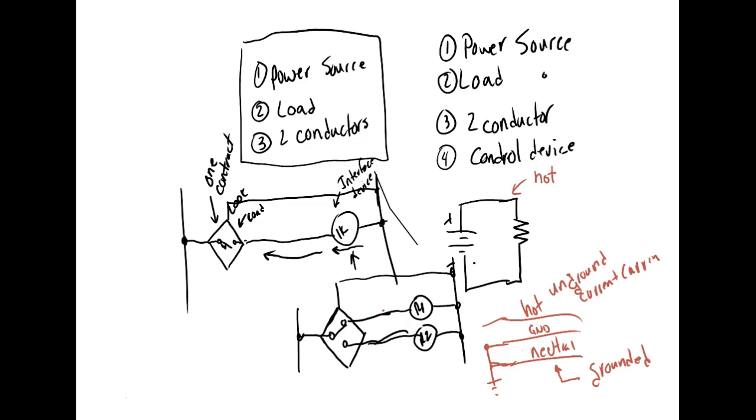Power up. Now make sure with your ohmmeter you don't put power into a circuit, so make sure you don't put your ohmmeter in here. What you're going to do is hook it up to the contacts, and the contacts right now are not wired up to anything, right? You understand? And what can you do down here?